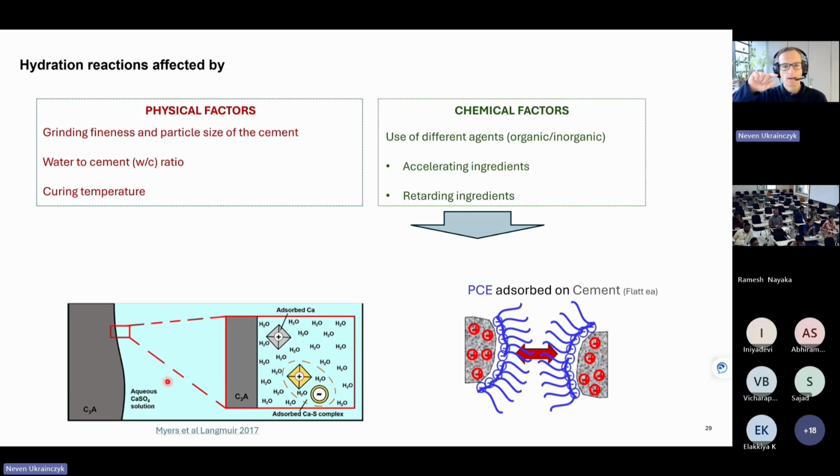of the reaction, and that's why we have this third peak for the aluminate reaction, which is very useful in calorimetry, in that we can optimize the sulfate amounts, which is not very important for the cement industry. It's also important for you, because when you use LC3 cement, new cements, then you have to optimize. Actually, the concrete technologists are doing this, because you are optimizing the concrete for the LC3 mixture.